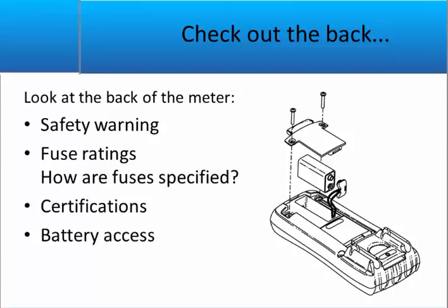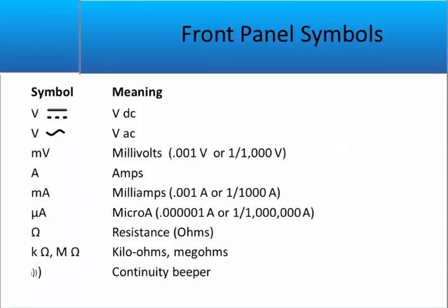The back cover is an integral part of the casing, so make sure it is in place and intact when you operate the system, because, as I mentioned before, it is highly likely that the full voltage which you're sensing is on the exposed metal parts under the cover.